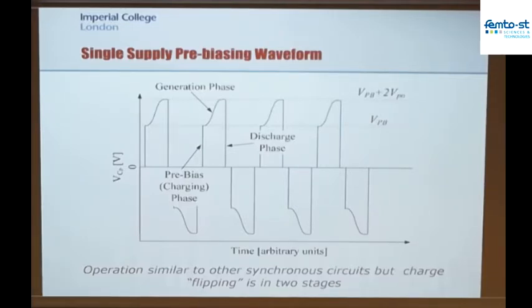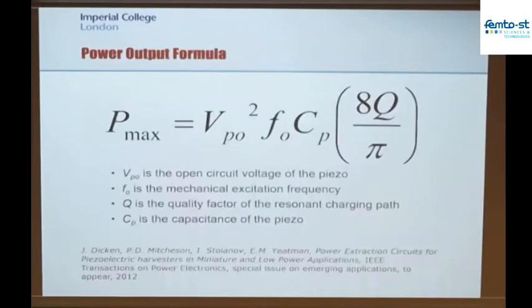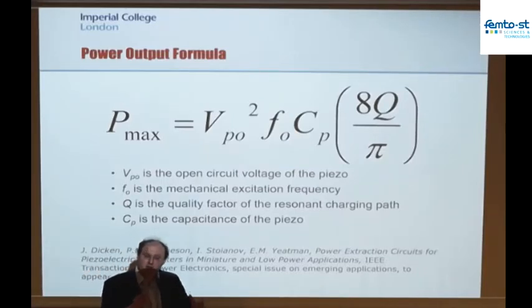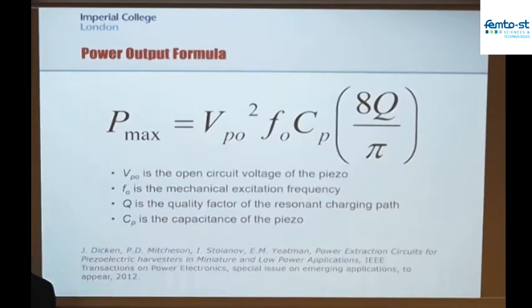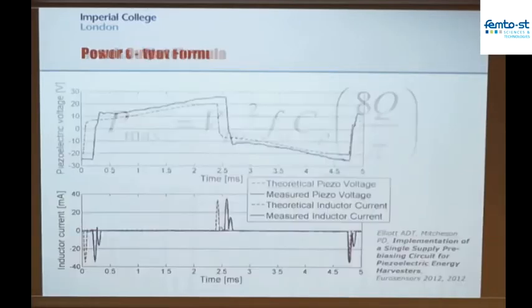Please keep in mind that the person who's designing the circuit to attach to your piezoelectric film is going to be very concerned with how high a Q factor they can get in a circuit that they attach to the piezoelectric material. And that's not just a function of the circuit, it's also a function of the piezoelectric material. If the series resistance of that piezo material is too high, we're limited on Q factor, and that will really limit the amount of power we can get out of this film.